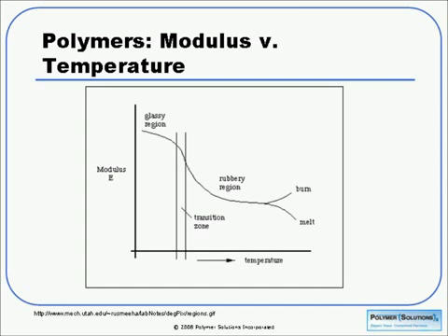You might want to know where this is. If you want a polymer that's glassy at room temperature, for example, you would know based on Tg that you wouldn't want to choose the polydimethylsiloxane we talked about a moment ago, because it's certainly going to be in the rubbery region at room temp with its Tg at -127. So that would be an application for this. If you continue heating, you may see a second drop for semicrystalline systems that corresponds to the melt of your sample.